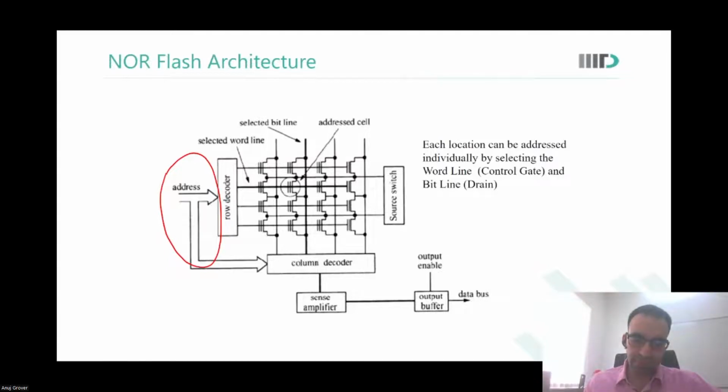Less resources. Yes. Again, this is very critical over here because flash is always off chip. If the flash would be on chip, then you need not have this multiplexing of row and column address on the address bus. But if flash is off chip, then there are a number of pins that are involved there, and that needs to be taken care of.